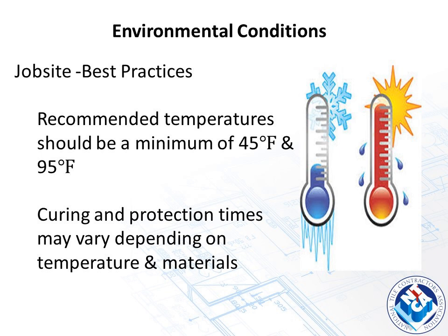Make sure that the materials are used in the proper temperatures. Most cement mortars are recommended to be installed between 45 degrees Fahrenheit and 95 degrees. Can they take more? Sure. Your mortars really aren't going to freeze till you get down to about 32 degrees, but they stop hydrating around 40 degrees. So you want the best performance out of your mortars on your job site. So really try to maintain the proper temperatures on the job site and it'll help your installation substantially.